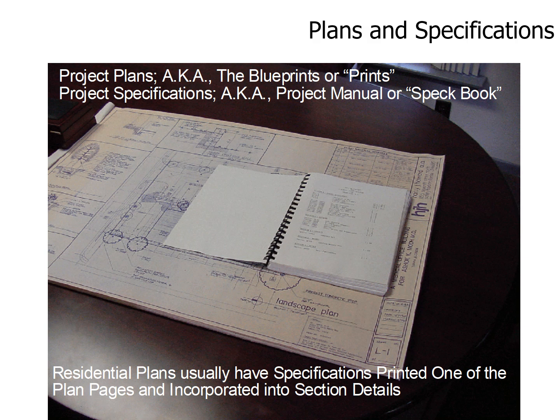Now, drawing documents and specifications. That's what I want to look at, and that's what the whole course is about, I guess, looking at plan sets and getting used to looking at them. Guys, there's only one way to get used to them, and that's to sit down with them and start doing little takeoffs. After someone else has done a takeoff of something, do the same thing. See if you can do it, and come up with the same answer they did.